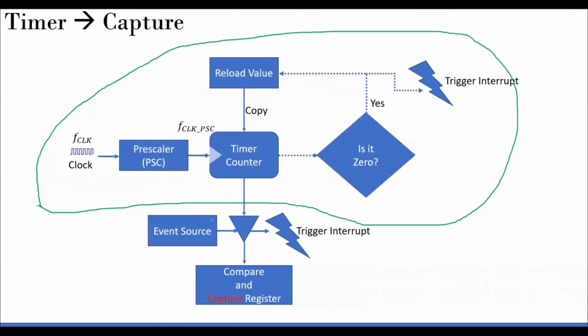So that's a capture mode. You give a capture register value. Whenever the timer value is equal to that register value, your input will be polled. And you have to write the code. That is an important aspect. So there's no magic here. You have to write the code. You have to write an interrupt service routine which will poll the particular input that you are interested in.